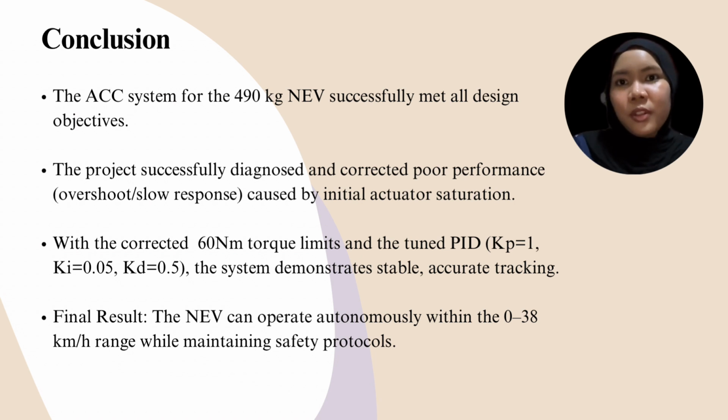So in conclusion, the adaptive cruise control system for the 490 kg NEV successfully met all design objectives. We identified and overcame a critical challenge. The initial poor performance, overshoot and slow response, was traced back to an incorrect setting in the motor saturation block. By correcting the actuator limits to plus minus 60 Nm and implementing the tuned PID values, we achieved stable and